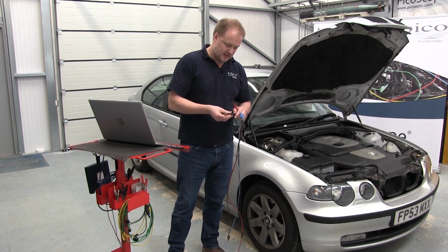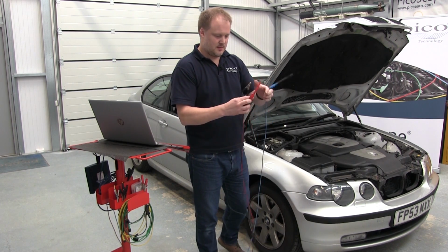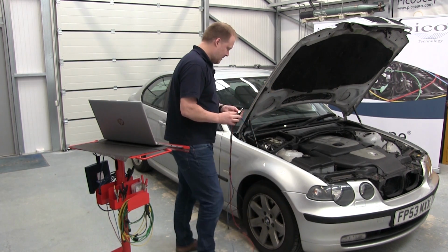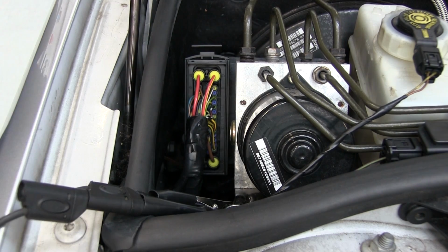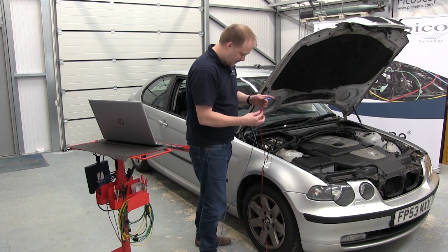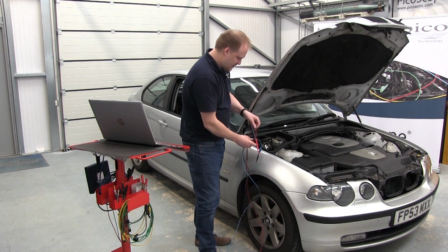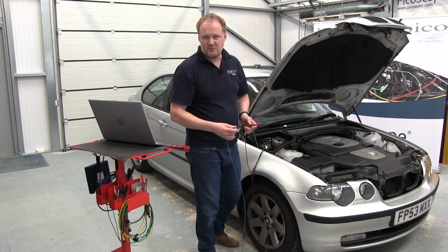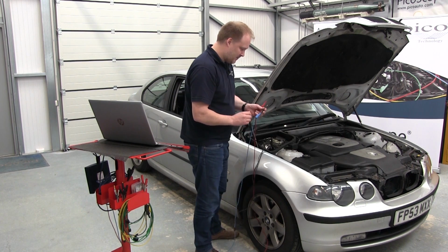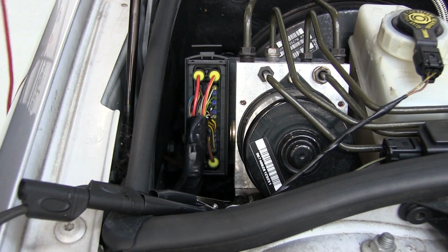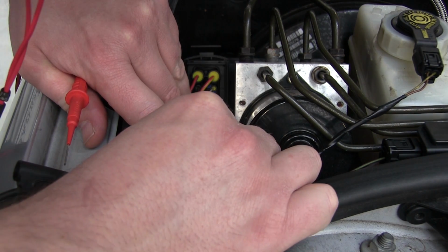So back to the same connections, no different. We've got our earth fly leads. Again, we've got a lovely earth connection available right at our fingertips, and now we need to back pin on the ABS control module. Obviously there'll be a lot of breakout leads involved otherwise, so we'll back pin. We can do CAN high, which we can put straight into pin 11.